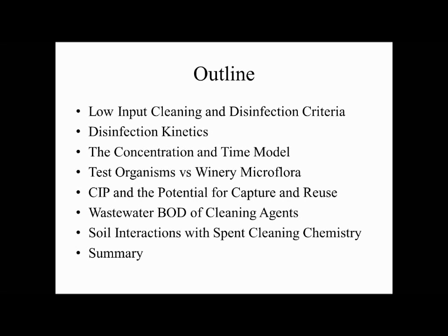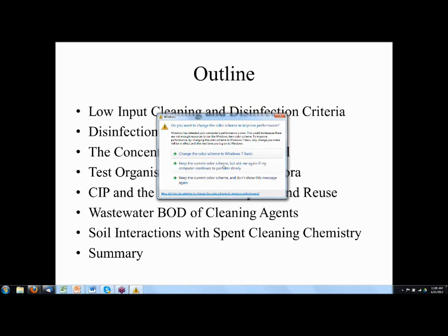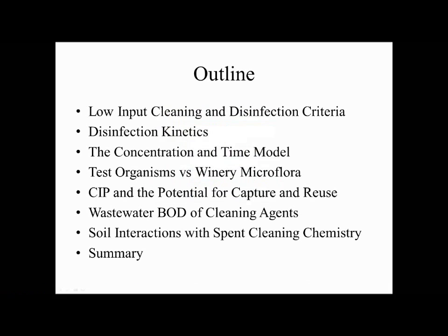And so we'll look at the disinfection kinetics. We'll look at an old reference model, which leads up to a line of understanding which says that the concentration that you have times the time that you have it in contact with the organisms is what determines the amount of disinfection that occurs.